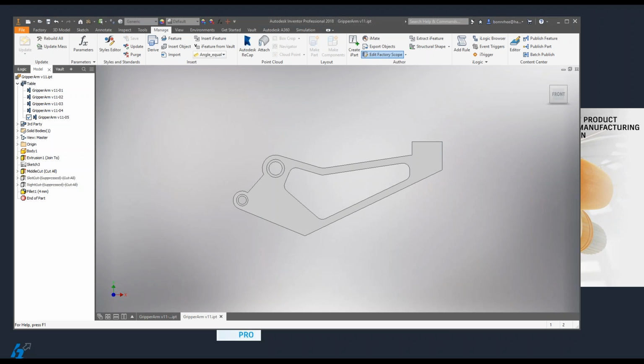All right. So the next question is, when using shape optimization, can you link the results to the model? And can you set up a sensor to warn you if you remove too much material? There is no sensor warning you about removing too much material. It's just a visual indicator from the mesh. I don't know what you mean by link, but you can just use an overlay.